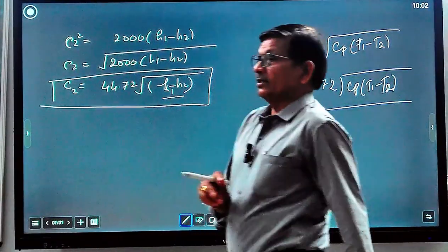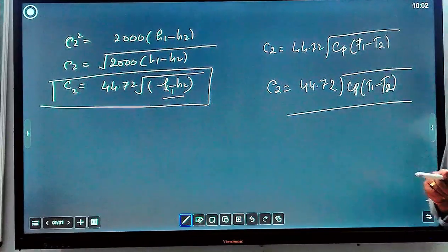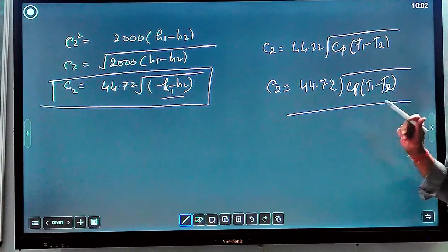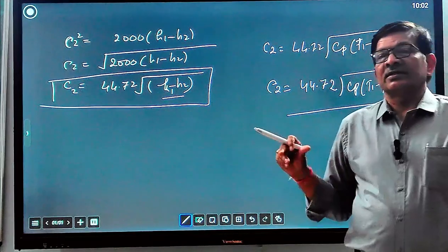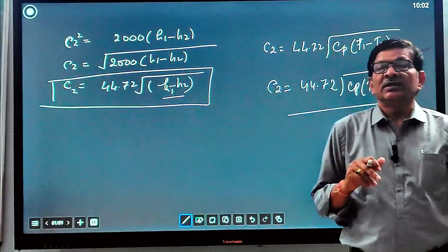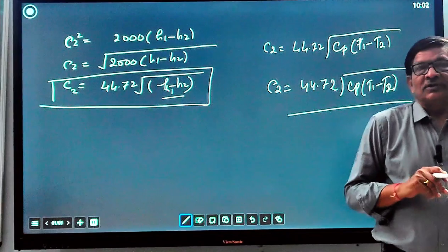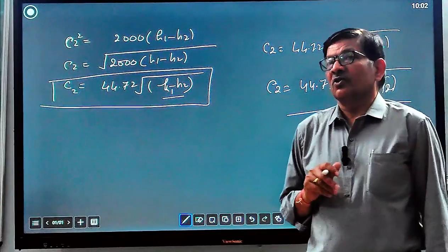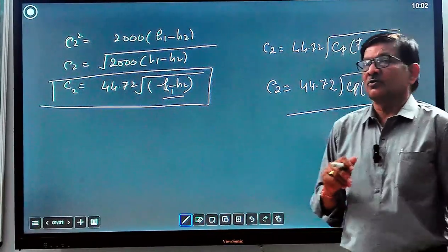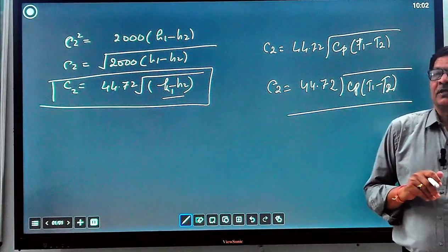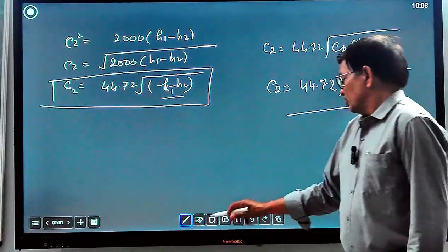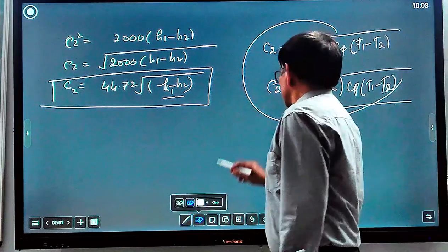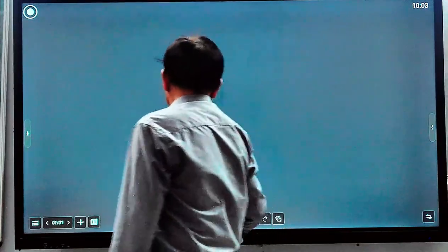This we have considered that there is no frictional losses, no change in entropy. This we have considered that flow is isentropic, but actually, in spite of the nozzle surface being very smooth, some percentage of frictional losses are always there, whatever surface smoothness you can maintain. So how can we calculate nozzle efficiency? Let us see nozzle efficiency.